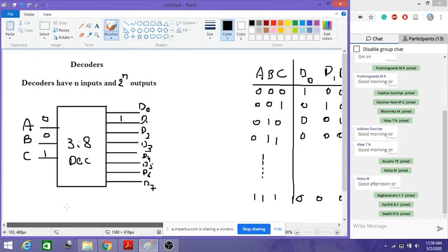Now we will come back to the application side of this decoder. You have some circuit which generates binary values. You can think of, say, a counter. A counter is a circuit which will generate binary values. We will see the counter circuits later; using flip-flops we can design counters. That counter is generating these 3-bit binary values, and based on that binary value, you want to make LEDs on. For example, you're making serial sets and you want to make them on. So how to make that?